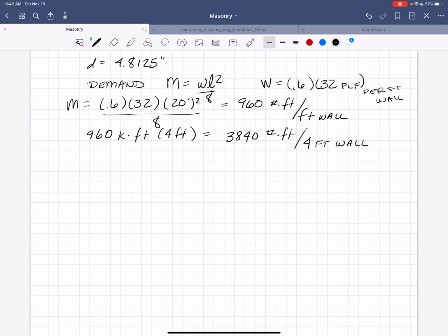I'm going to go ahead and start out by assuming that this is not a T section, so I'm going to assume that kd is less than the thickness of the flange. At that point, whether it's over or under reinforced, M is still Kf times b d squared.